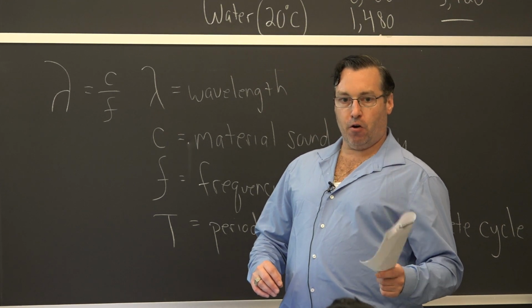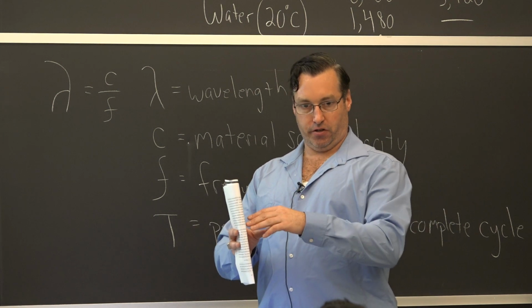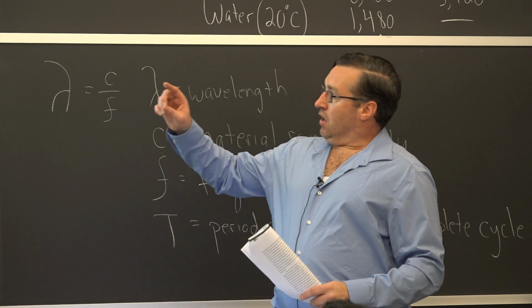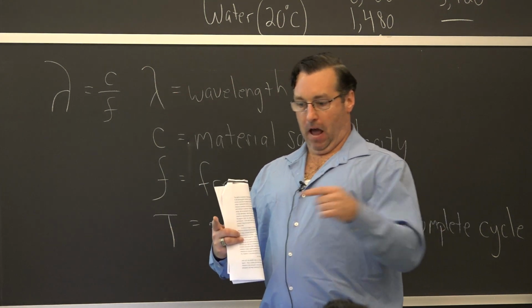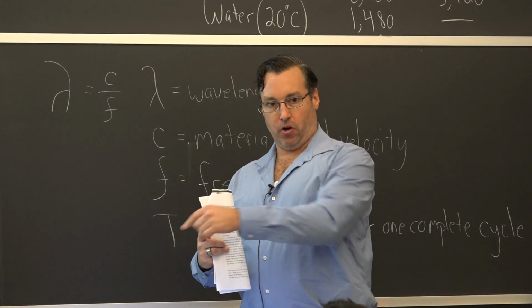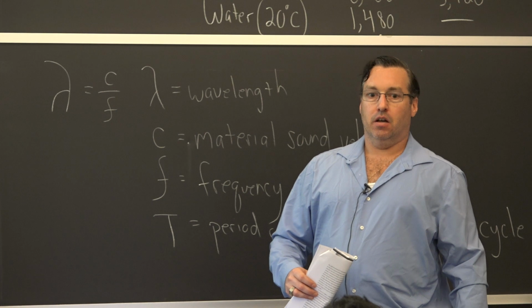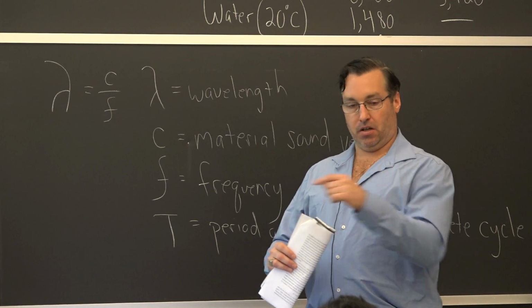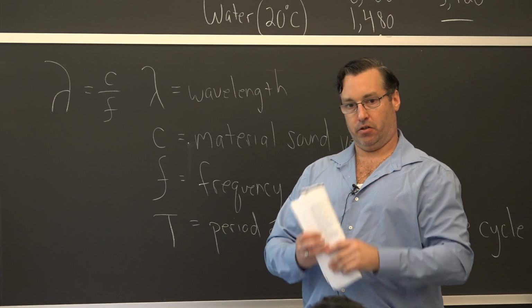Well, it's a trade-off between the resolution of the inspection and the penetration. It goes to the longest dimension, all right? What's the distance that it has to travel and come back? So does higher frequency mean more penetration or more resolution? Higher frequency means it can penetrate further in, but it sacrifices the resolution of the inspection.